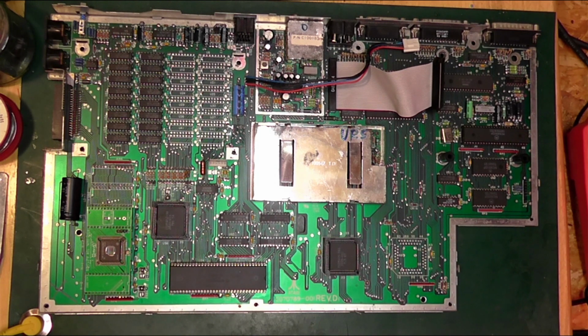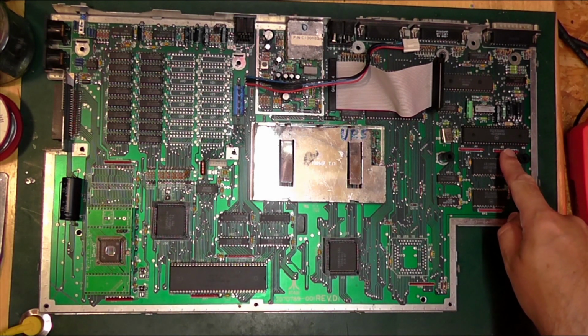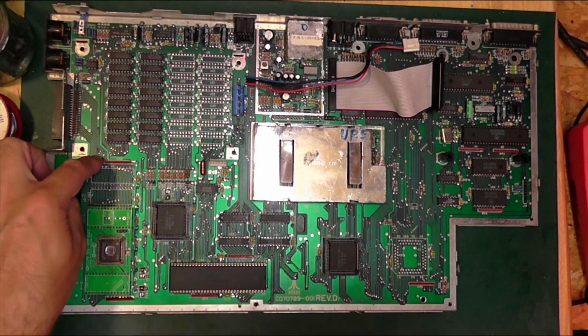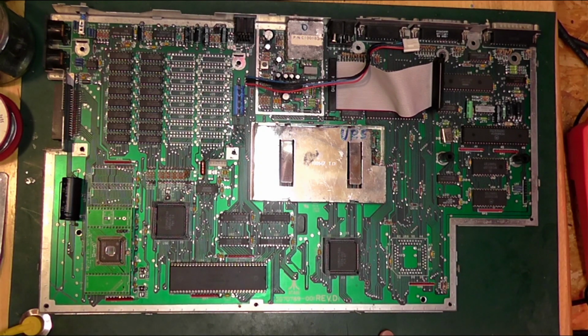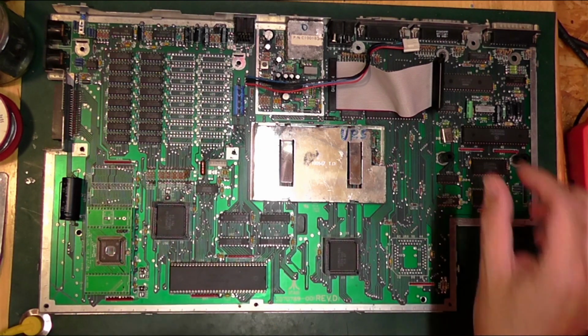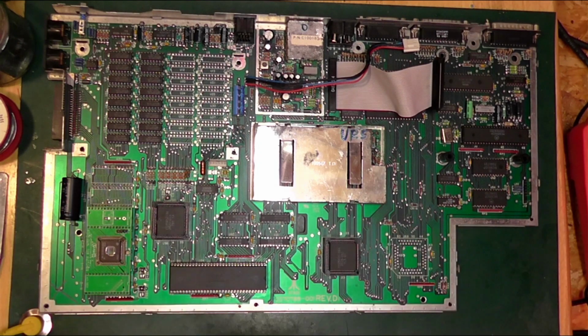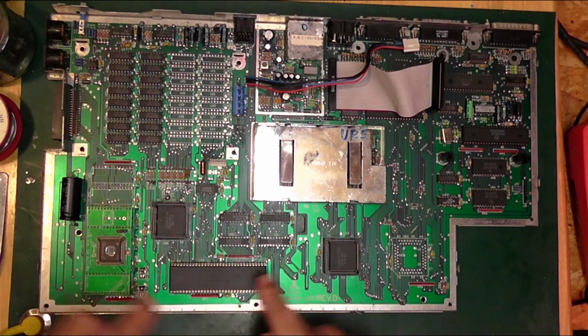So the resistor networks in question, there's RP2 over here, these are the red ones, RP3 down here, RP8 here, RP4 down here, and RP, I think that's 6 up here. Those are the networks in question. Now, the recommended way to do this is that you desolder all of these and replace them with approximately 2.2 kilo-ohm resistance packs. The way these work is that one end is tied, so they're a common bus.